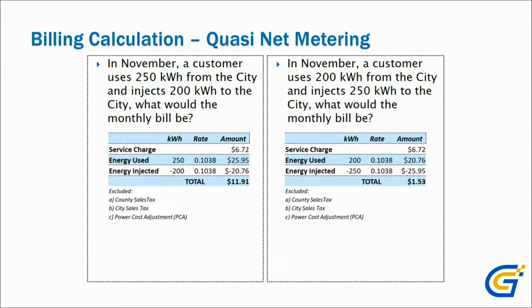The 1% is that your system cannot be greater than your actual demand for one year. So right now you can be as high as 1%. Yeah, 1%. That's what I'm saying. On the parallel connection, you can go up to 4% as your maximum. So it's tied to whether you go parallel interconnection or net metering.